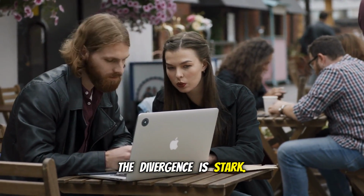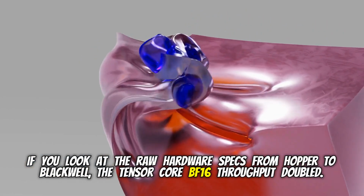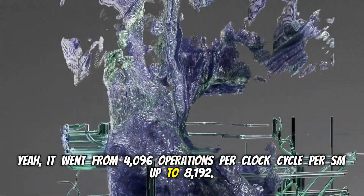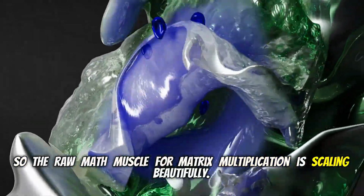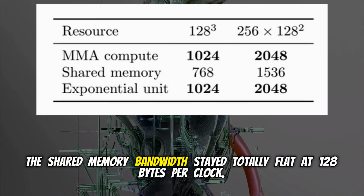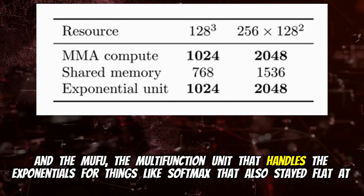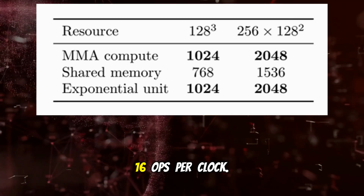The divergence is stark. If you look at the raw hardware specs from Hopper to Blackwell, the Tensor Core BF16 throughput doubled. It went from 4,096 operations per clock cycle per SM up to 8,192. So the raw math muscle for matrix multiplication is scaling beautifully. But the other parts aren't. Exactly. The shared memory bandwidth stayed totally flat at 128 bytes per clock, and the MUFU, the multifunction unit that handles the exponentials for things like Softmax, also stayed flat at 16 ops per clock.